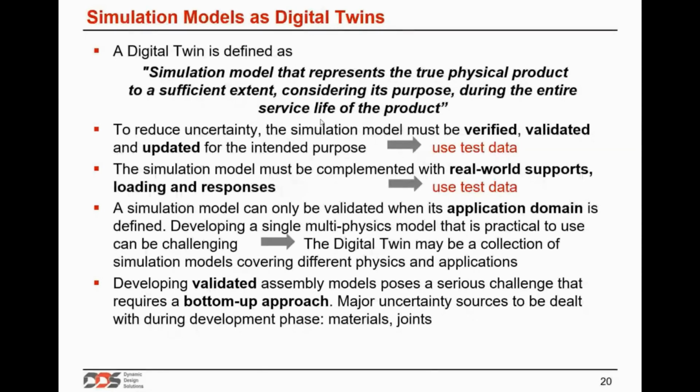So if any changes are made to a bridge, like retrofitting or reinforcements, or even if damage has occurred, that should be introduced in the simulation model to keep it up to date. And so that means that model updating then becomes a permanent and a continuous part of the system.